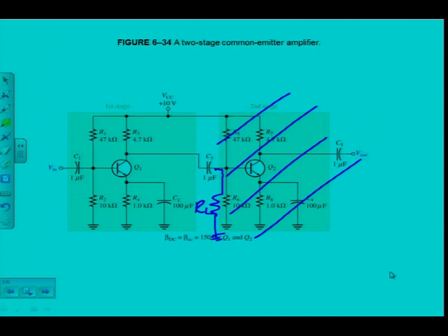And we've also determined that the maximum voltage gain of the common emitter amplifier was RC divided by R'E. And remember, don't go and learn this by heart. You have to go and look at the amplifier that we work with. Is this formula true for the amplifier that I'm given?